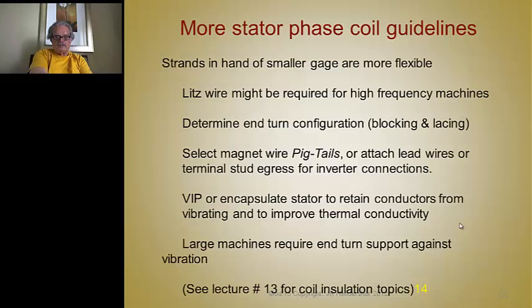And your terminations and lead egress depends on whether you use magnet wire pigtails right out to terminal studs or whether you attach lead wires to the pigtails and bring lead wires out for connection to the inverter. And then VPI or encapsulating the stator to retain the conductors from vibrating, improve thermal conductivity. And as we said, large machines require end turn support against vibration. And for insulation topics and details about how to insulate the windings, see lecture 13.